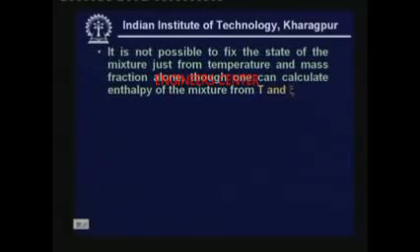That I will discuss a little later. Also, it is not possible to fix the state of the mixture just from temperature and mass fraction alone, because one can calculate the enthalpy of the mixture from temperature and concentration, but you cannot say whether it is in the superheated region, subcooled region, saturated region or two phase region just by knowing temperature and composition.